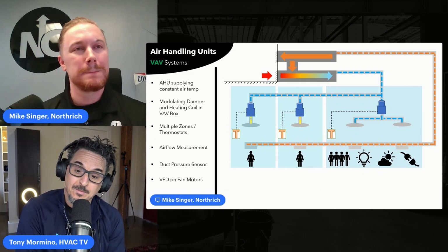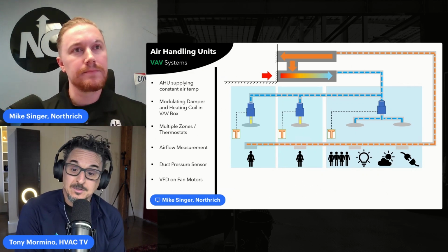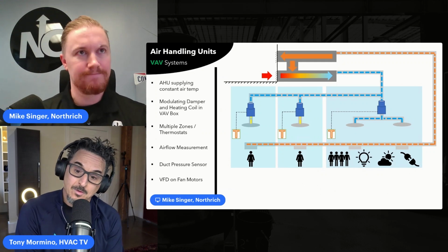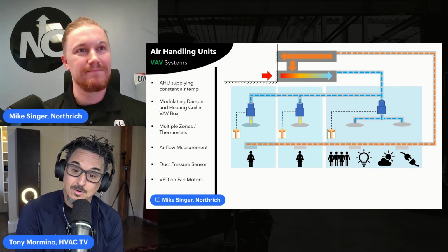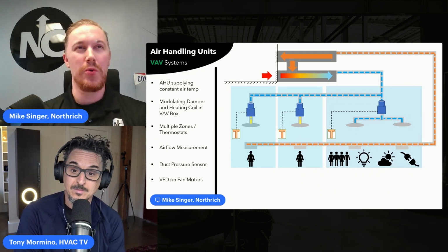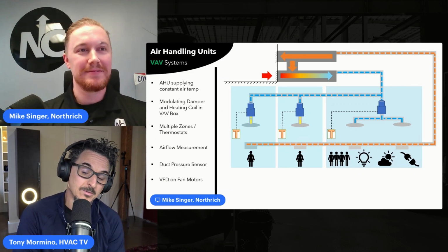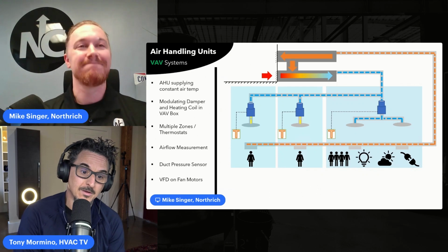That's such a good point. I actually had a job where it was specified 180 for the water, and it was specified 1 row coils, but they changed it to 140 and it didn't get caught in time. So all the boxes we shipped had one row. I think they had to be all retrofitted because that won't do it at 140.